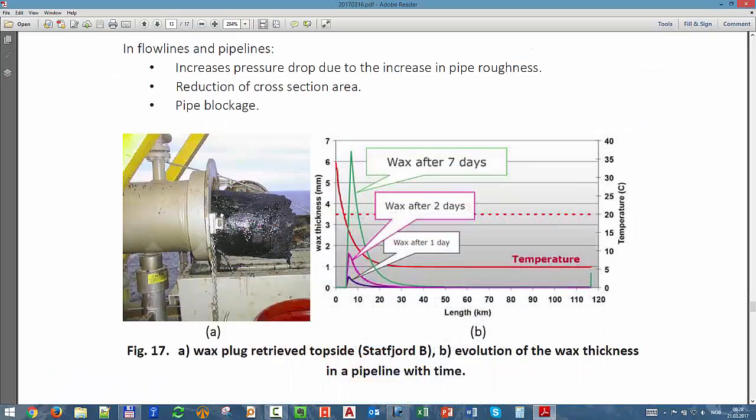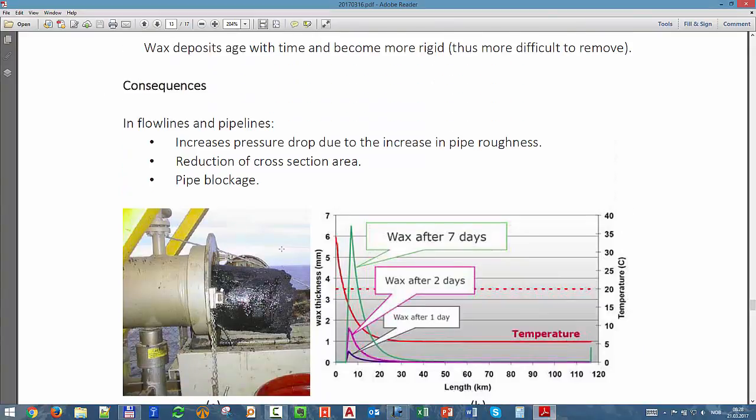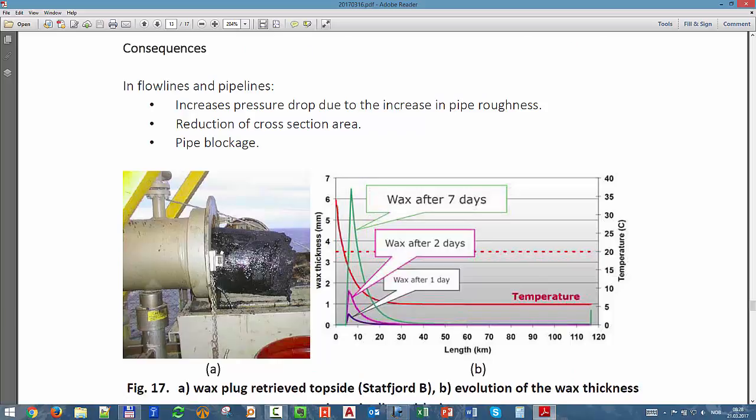But going back to the question, here you have really a mixture of asphaltene and wax. The main thing is that waxes precipitate and they try to join or grow around asphaltene particles that you have in the fluid. So all the time when you have waxes, you usually have asphaltenes, and they help in the nucleation process to grow these wax crystals. But they are very different